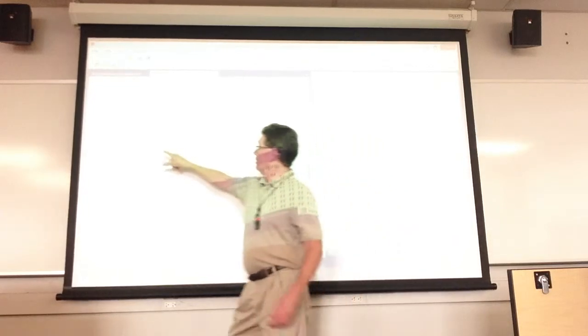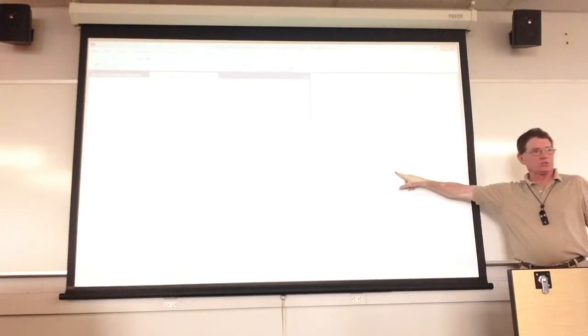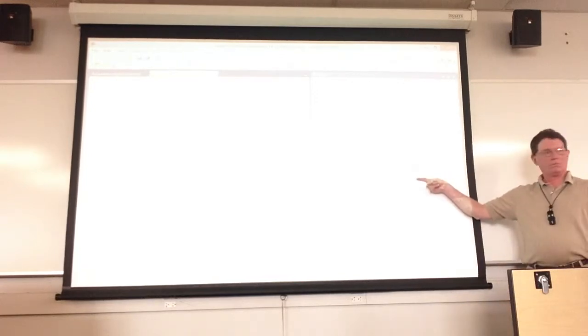All right? Right here. Now we're going to load in 5 into R17, whatever. It's just an example. Then we're going to add those guys together. And now we're going to output that result to port B. So if I go back to my I/O view, click on port B, you can see it's set up as outputs. The data direction register for port B is all high. And now I take the number that I had, the 8.5 that is in R16, we added 5 to it, and now we're going to output that to port B.